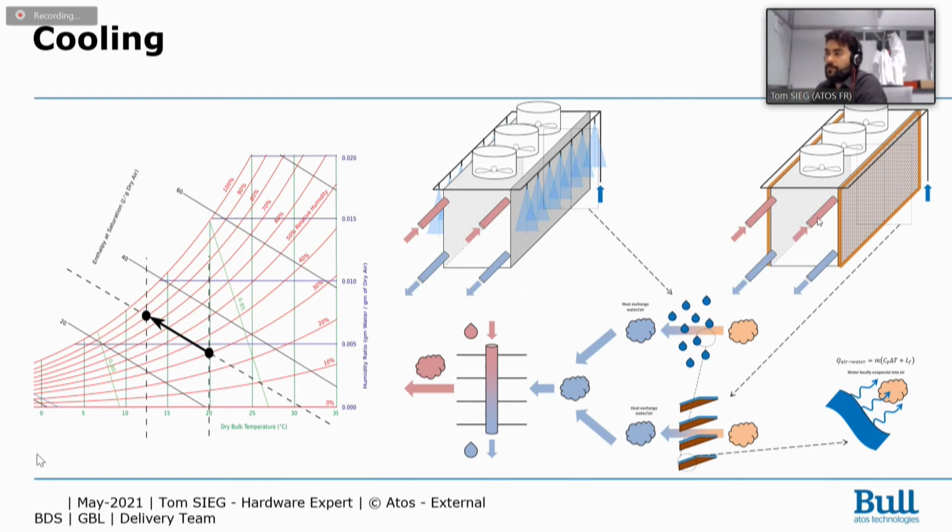We go in with hot water here, and the air from outside will cool this internal water so it goes out colder. To optimize this heat exchange, we optimize the size of the contact area, and we also optimize the air contact with fans.